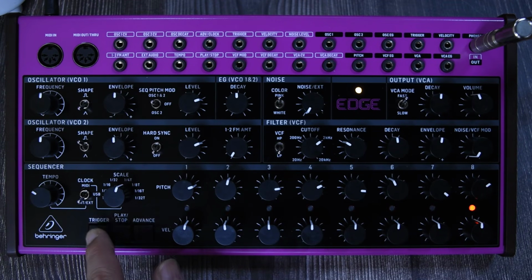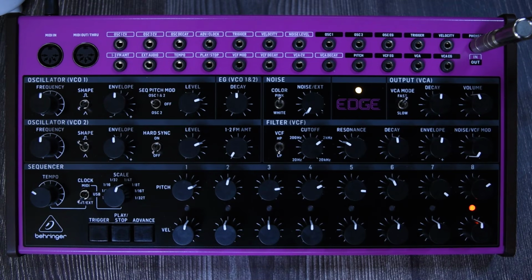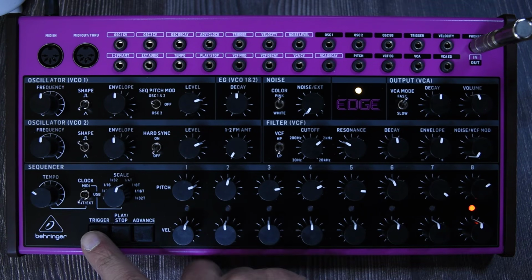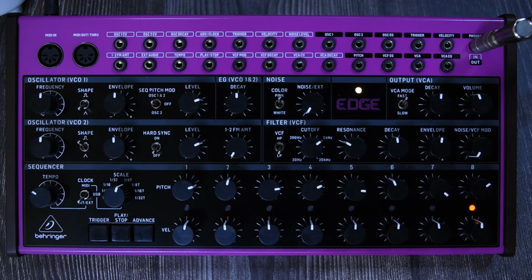Same thing right here. This is the trigger button. Every time I tap it, I'm going to be playing whatever position. So we are triggering the envelopes. So this is what it does, it's going to output a voltage, right, to the envelopes. And it's going to be from 0 to plus 5 volts. But it's a pulse. That's why it's called a trigger and not a gate. It's a very short type of instruction.